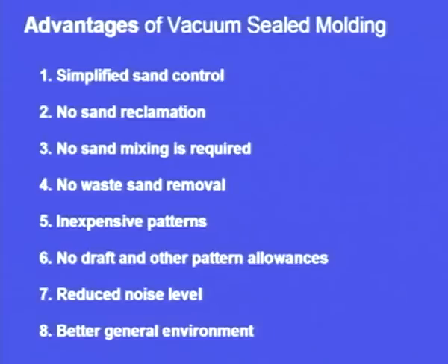And next advantage, better general environment. In the case of the conventional sand casting process, we add clay, that leads to poor environment. The environment will be polluted, especially after solidification. When we break the mold, dust will be rising, and here there is no such thing. We are not adding any clay. So here the environment will be clean.